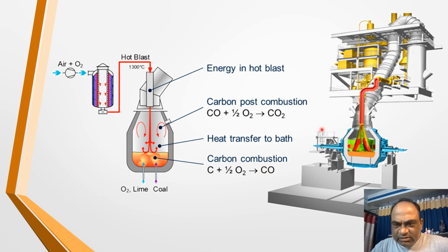Here in another picture, you have been shown how this tilting mechanism works. This is the vessel part, and it is supported on two sides so that it can tilt. On the bottom side you will have the slag car on one side and the steel car on the other side. The steel car will of course carry the steel ladle and the slag car will carry the slag ladle, and the vessel is tilted to pour the steel into the steel ladle.